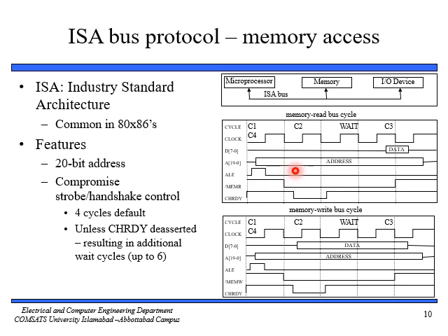After C2, it is going to read the data till C3, and after C3 we are putting the data on the data bus. You can see here the data, and after C4 all the signals are deasserted.